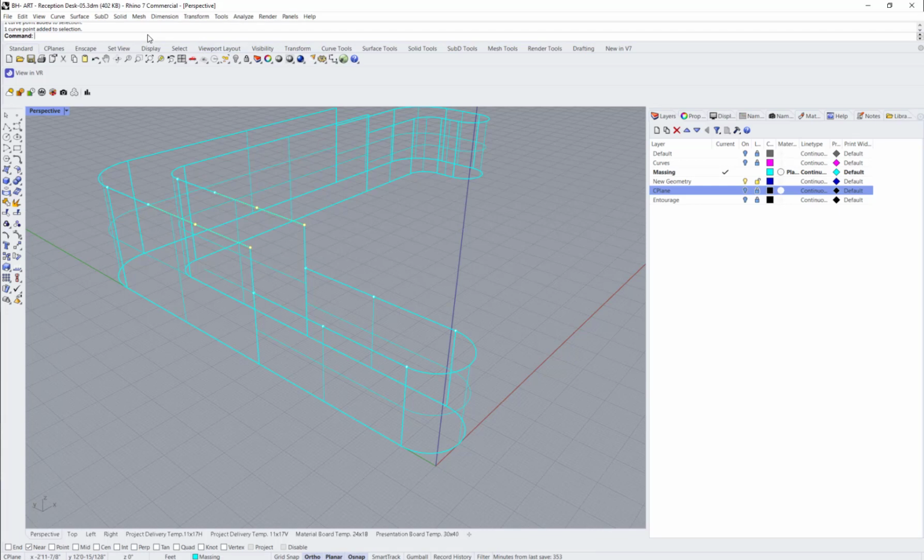So in the command bar, we'll type set point, and then we're only interested in moving it in the Z direction. And you can see here, we'll go ahead and snap to the end. Therefore, because both of these points, the second and end point, fall along this vector, we know that the two curves will remain tangent to one another.